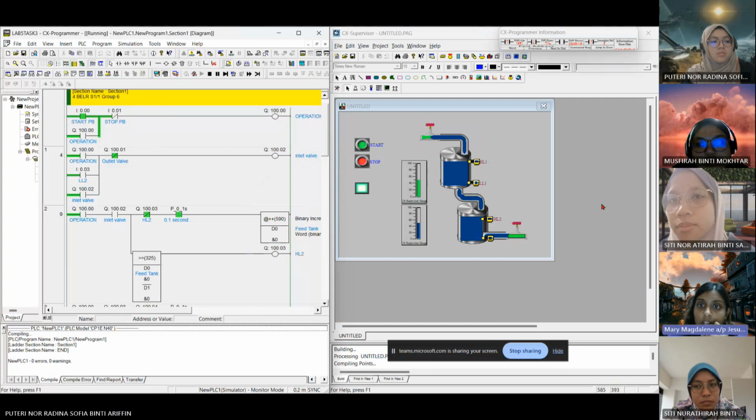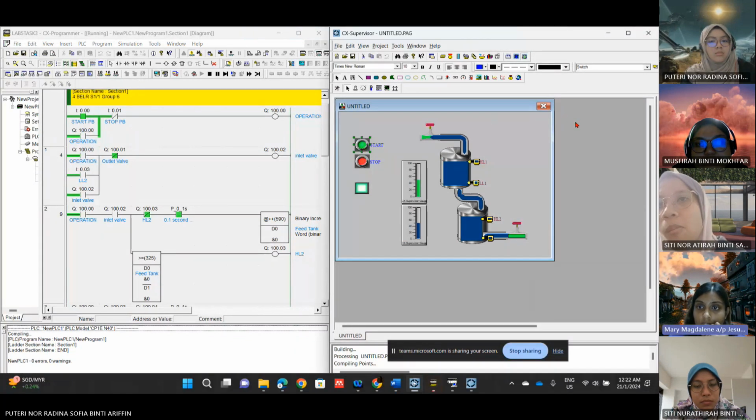Ensure a safe initialization state, setting the feeder tank's initial level to low level sensor 2 and initializing switches and valves to default closed positions.